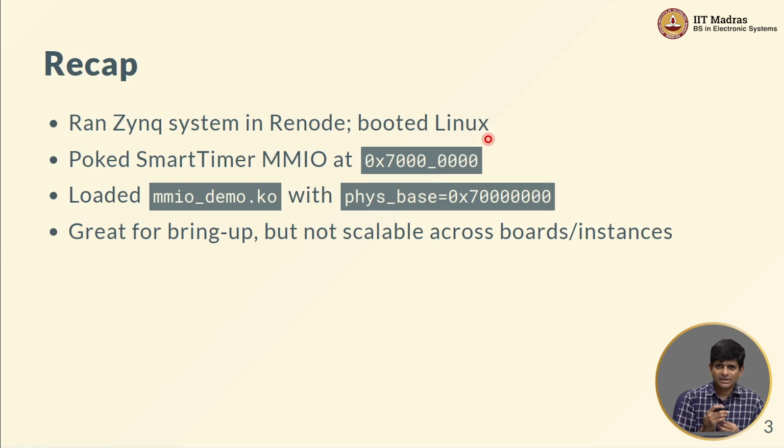So the DTB is required not so much for enabling the system boot up as such, but primarily so that the kernel as it boots can identify the various kinds of hardware peripherals attached to this particular system, and can also decide on where the output messages, for example, need to go.